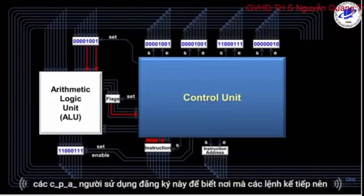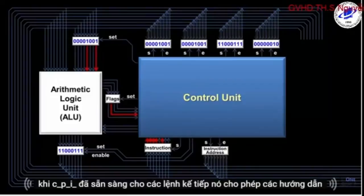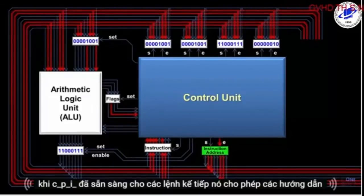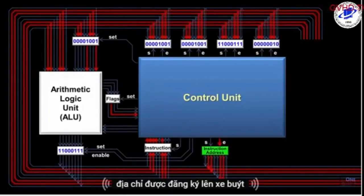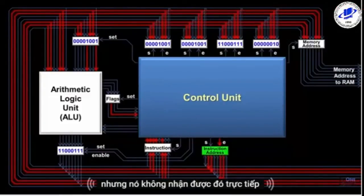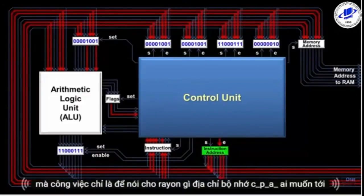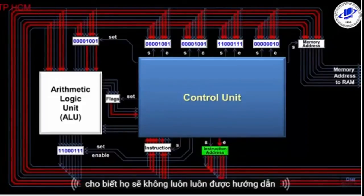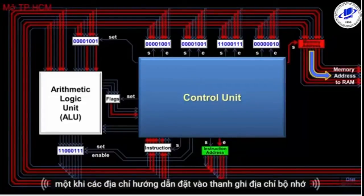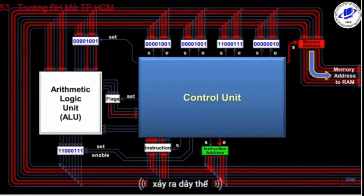The CPU uses this register to know where the next instruction should come from in RAM. When the CPU is ready for the next instruction, it enables the instruction address register onto the bus. Eventually, the instruction address will flow to RAM, but it doesn't get there directly. There is an intermediary register called the memory address register, whose only job is to tell RAM what memory address the CPU wants next, since it won't always be an instruction. Once the instruction address is set into the memory address register, it is automatically sent to RAM since the memory address register doesn't have an enable wire.